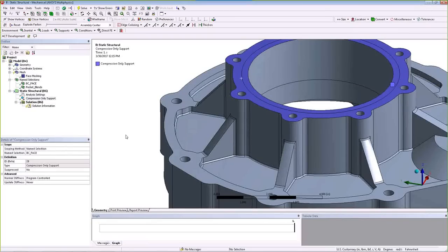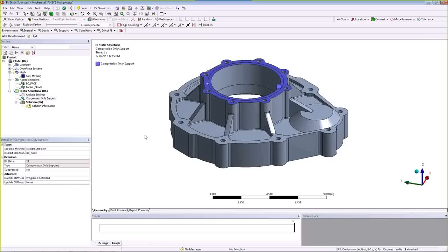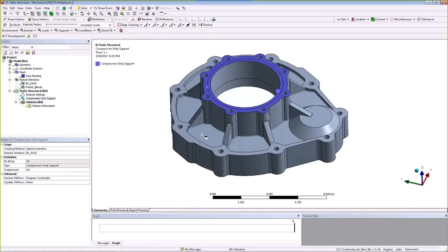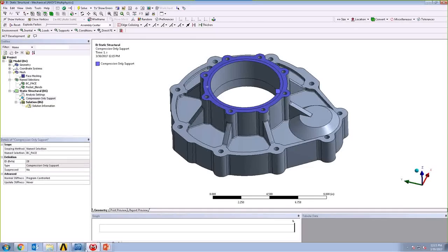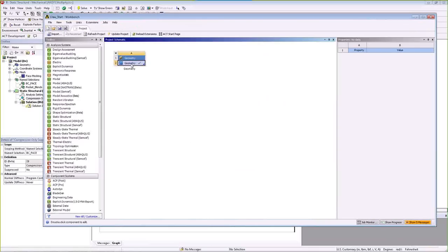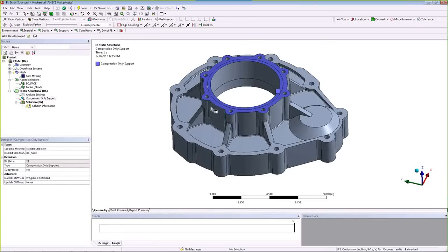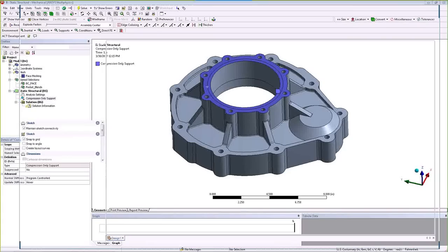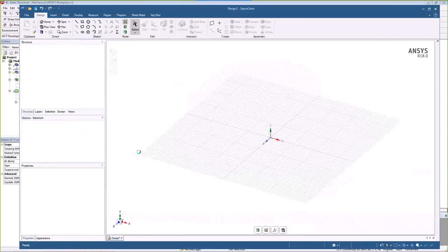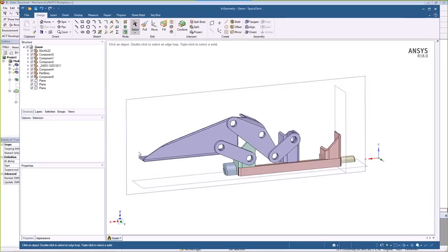So that's the way that we'd want to go and set up our model, is to make sure that when we're performing these geometry changes, that all of our loads and boundary conditions stay on the model so we can quickly perform some design changes. Okay, so then the next thing we can do is if we wanted to parameterize a model in a slightly different way, but say effectively the same thing, we can do something similar where we create some dimensions and then we parameterize those dimensions.